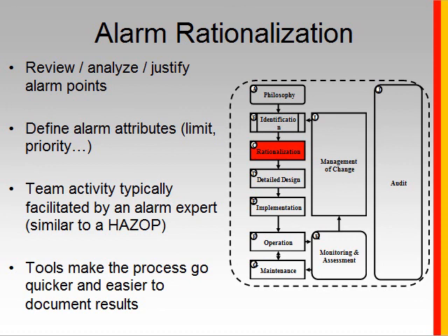So again, during rationalization, we're going to take a systematic review of the alarms to make sure that they truly deserve to be alarms or should be alarms. We're going to analyze the limits, set the priorities. Now, this is typically a team activity facilitated by an alarm expert. If you're familiar with HAZOPs, it's very similar in terms of the workflow structure for an alarm rationalization.